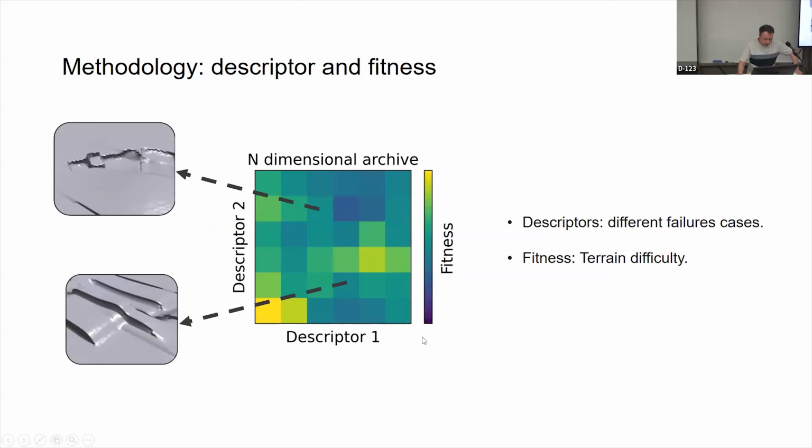So here, for the diversity, instead of considering the diversity of the terrains themselves, what I propose to do is to create 6 different penalties, and each penalty corresponds to one behavior from the controller that we want to avoid. So basically the behavior of the robot when it travels the terrain. So for instance, it can be when there's a collision or when the robot does not respect the command input.